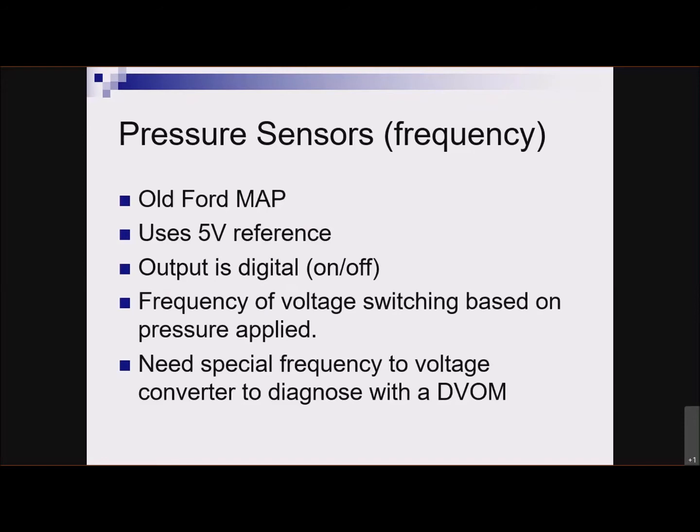But they didn't give you any specs for what the hertz ought to be. They had a MAP sensor tester that converted to voltage you could plug into a voltmeter. Most techs, honestly, carried a MAP sensor in their toolbox, and they tested it by plugging it in. It was just way faster. That's not really a recommended way of diagnosing, just slapping parts on, but in some cases, it made sense.